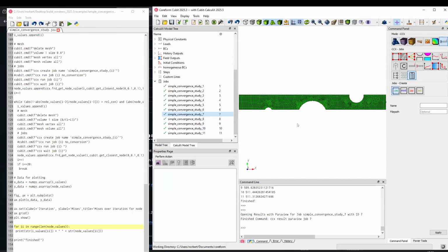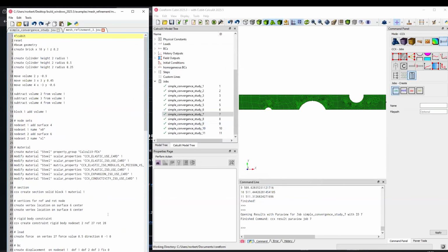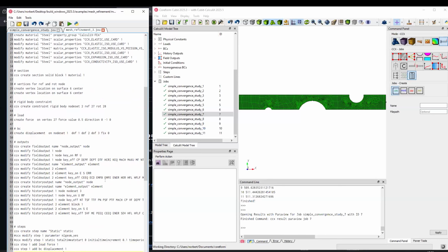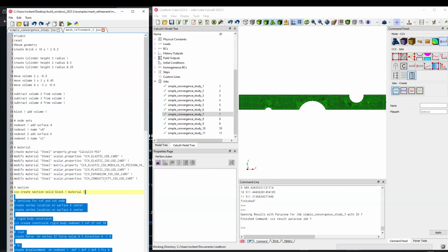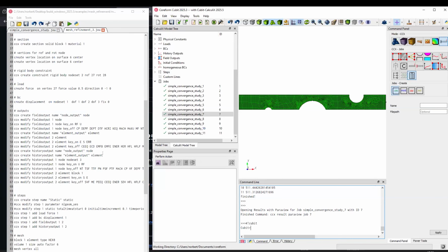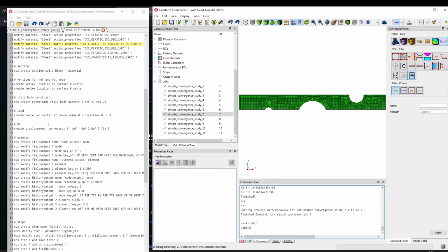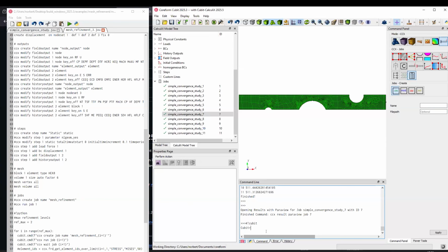The other thing that I want to show is that if you have access to your results, you could even try to make a refinement based on those results. Basically, just copy paste here again. Yeah, that's the best thing about Qubit. You can't get lost. You don't lose any progress when you more or less make an error in your meshing or a model setup process. You can just take the step back. It's wonderful.